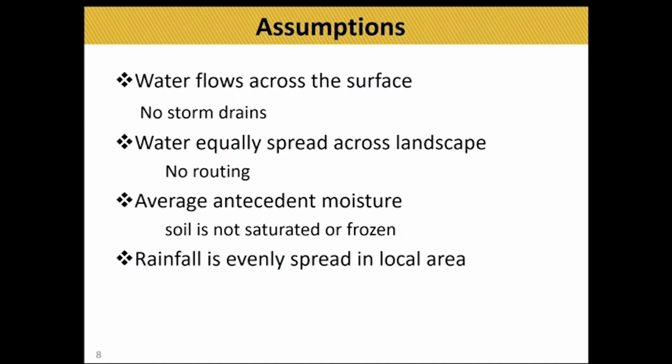And so in a world like that, you would have to put in a value for how saturated the soil is. Because we're using real observed data, we're not using anything in the winter, so the ground's never frozen, because that would greatly change our calculations. All the water runs off on frozen ground. So basically in our model, it's a day in June every day that we run our model.